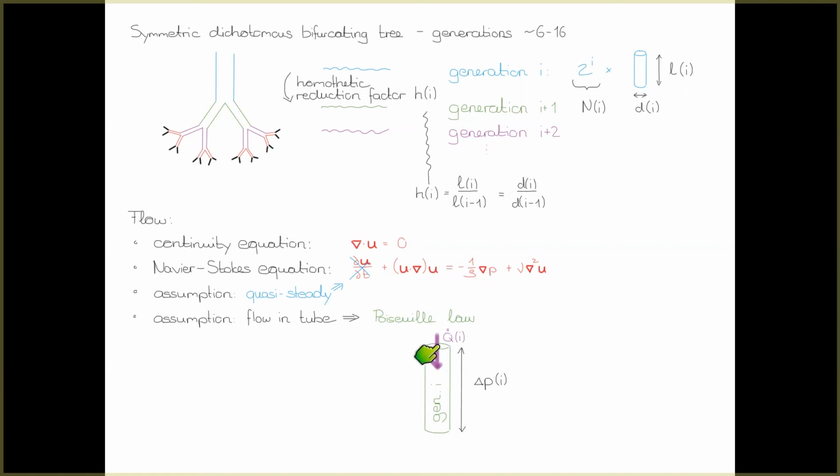and integrate over a diameter, it cannot be that we have the same flow rate, but we should have the same flow rate because the mass flow rate is given. But if the flow is maintained and not slowing down, there must be a compensation of that momentum loss, and that's through the pressure gradient. That's why we have a pressure drop here.